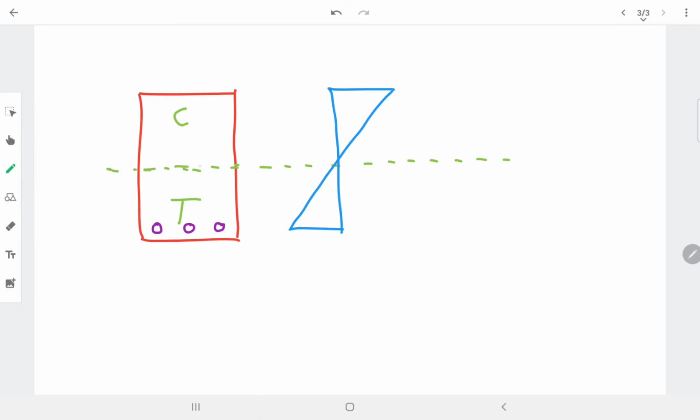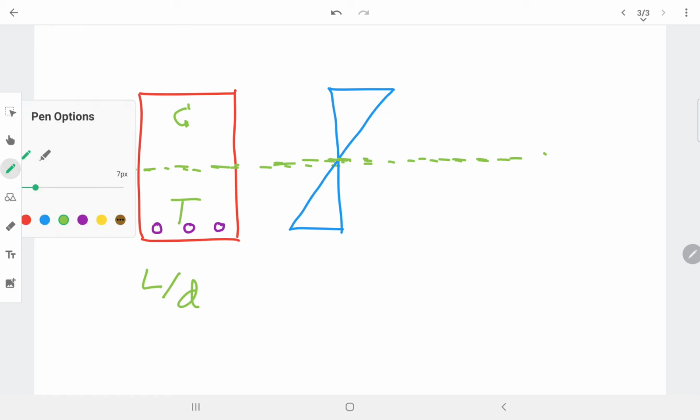Here the neutral axis is exactly passing through the center of the beam. So the strain above the neutral axis as well as below the neutral axis are equal. Now, whatever the L by D ratio is there, you have taken this same as it is, the top fiber of the concrete under compression and bottom fiber of the concrete under tension. As you know, the concrete is weak in tension, so you have provided the reinforcement, that is AST, area of steel in tension, on the tension side.